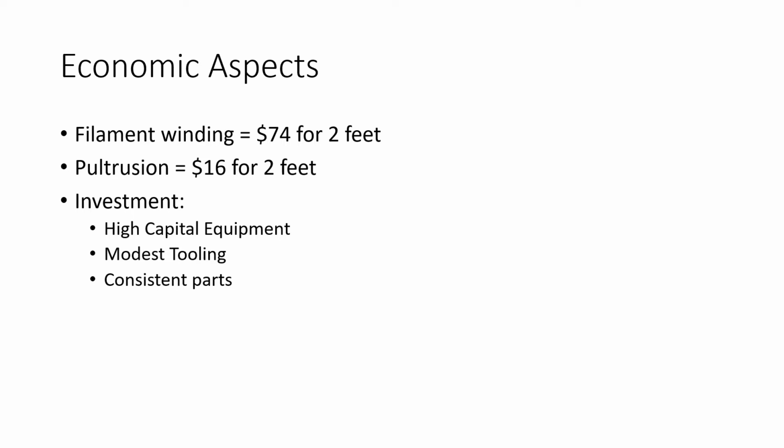With the pultrusion process, a die can be anywhere from $4,000 to $25,000. However, the lifespan of this die can be around 150,000 linear feet. On the other hand, a mandrel for filament winding, a 48 to 60 inch long steel mandrel with a 1 to 2 inch diameter, can cost between $50 and $100. However, a chrome plated mandrel can be between $250 and $500 with the same dimensions.